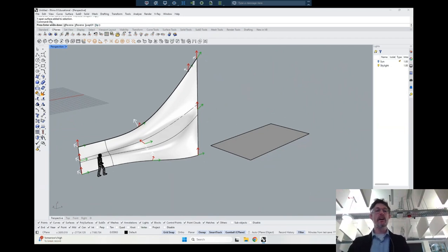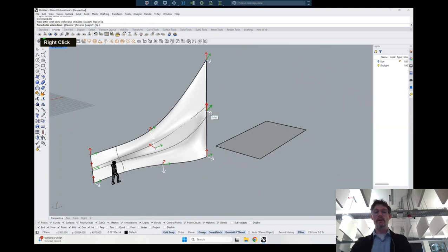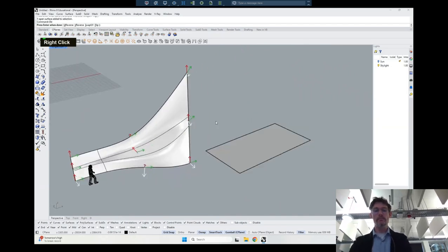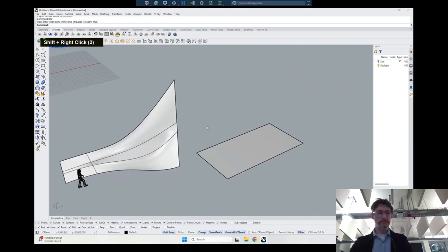When you've typed dir, which is just direction, you can flip it. So I'm going to say flip, there it is, and now all the white arrows, the butter of the toast, are pointing in the direction that I actually want. I'm going to press enter, and now if I type dir again, it will show me those white arrows firing towards me rather than away from me. So that sets me up fairly well.